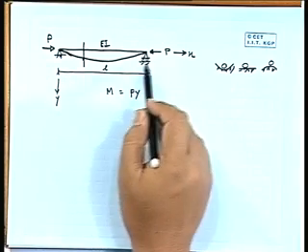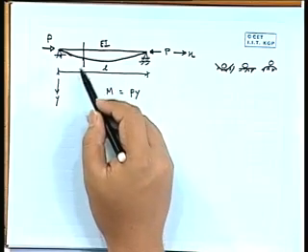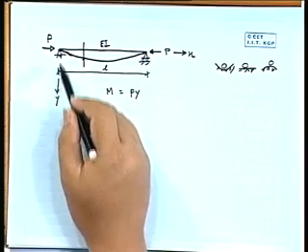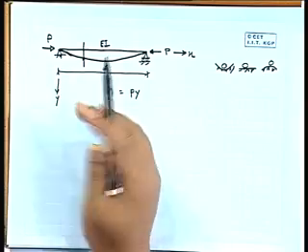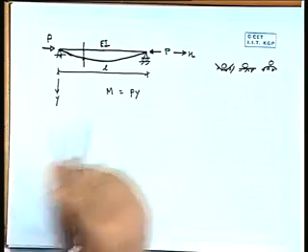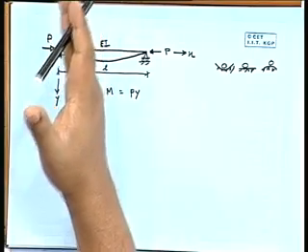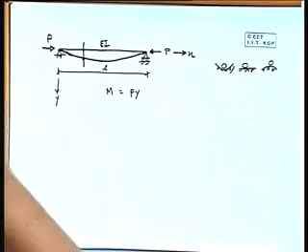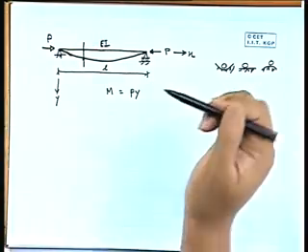This is after the deflection takes place, when it is in the deformed condition. So what will be the moment here? There is no reaction here, so reaction into distance we are not getting, but this force into that distance gives some moment. Or we can cut that section and take the left piece. There is a P, and the distance is y, so P into y moment will be coming there. In any way you investigate the problem, you will get a moment that is simply P into y. And what will be the type of moment? Here it will be a sagging type of moment.